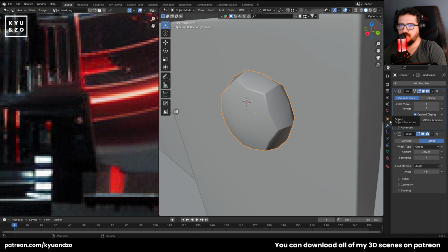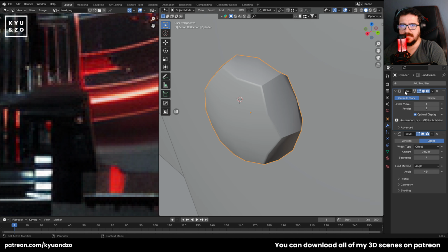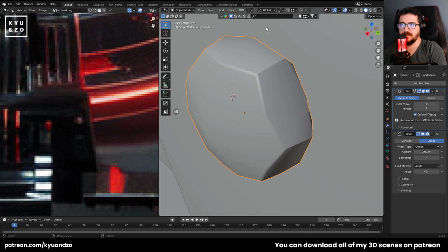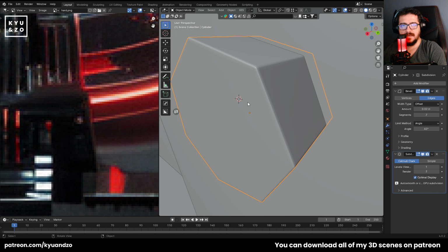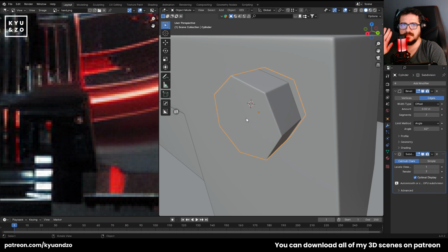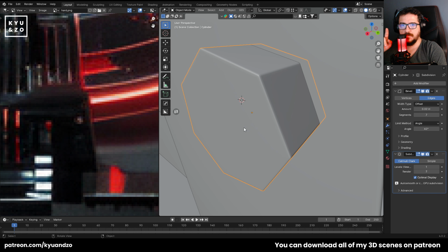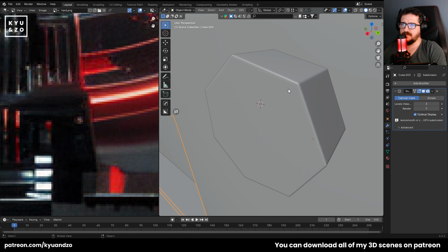You are saying to Blender to make the subdivision surface first, and it says okay, I made it, and this is the new shape, and after that it's gonna bevel the subdivided surface. If you change the order, now it's gonna bevel the simple shape, and after that you are saying that now you can add subdivision surface. Now that's a different shape here. Okay, don't forget that. So we have this shape here.